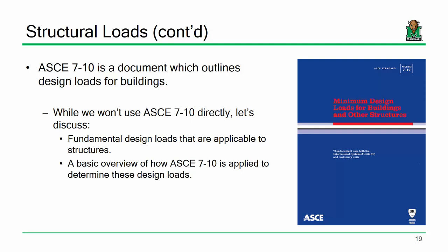And the answer is these come out periodically. Right now we're using ASCE 7 2010, and they're currently trying to adopt ASCE 7 2016, although I guess it should be 2017. But these things get periodically released every so often. And you'll see things like changes in the snow maps and changes in the wind speed maps. ASCE 7 just recently redid how they address wind altogether. That was a very big overhaul to the spec.